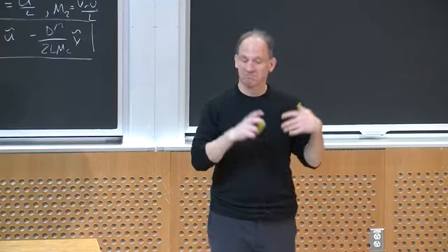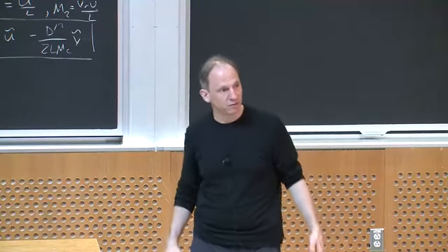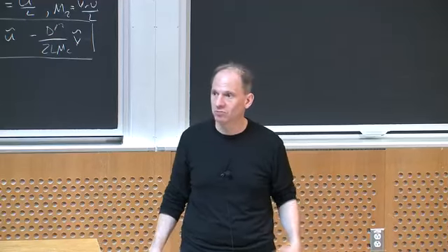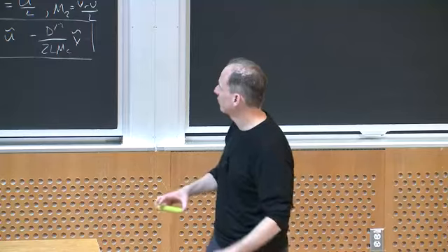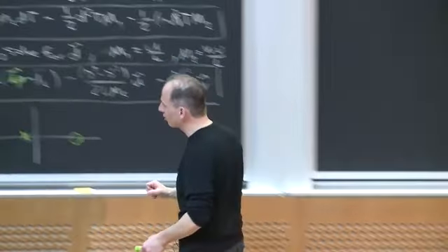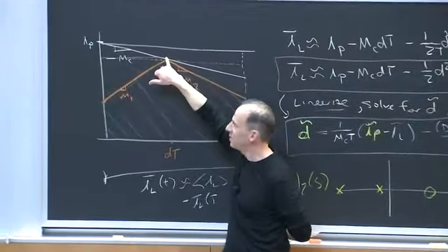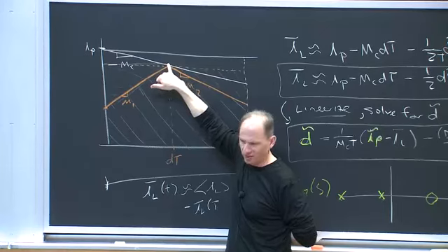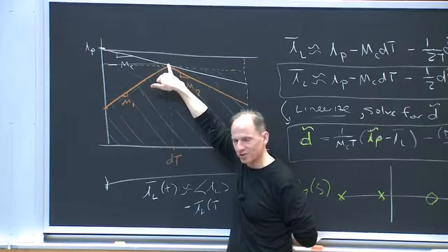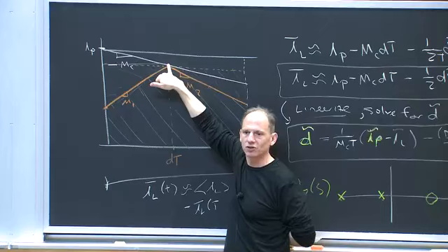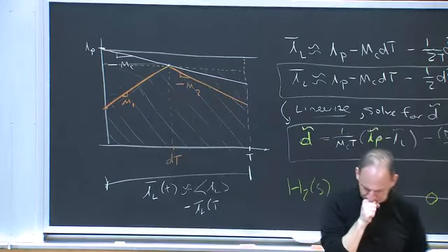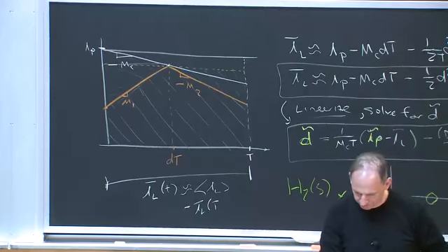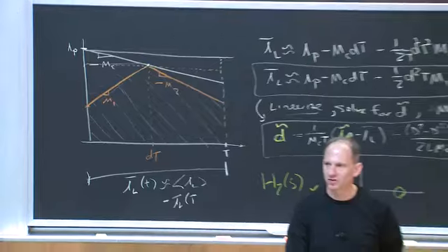And in fact, if you're designing most kinds of PWM DC-DC converters, most of the control chips on the market are going to use current mode control. This version that I'm showing you is called peak current mode control because you're controlling the peak of the inductor current. And that's the most common kind. There's also valley control, and there's a few different versions of this general idea, but this is the most popular one. Okay? So that's one trick. Any questions up to now?